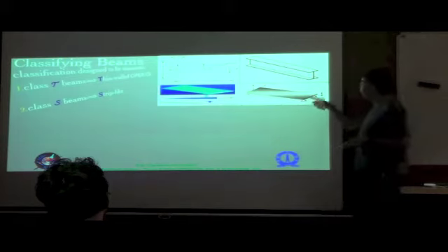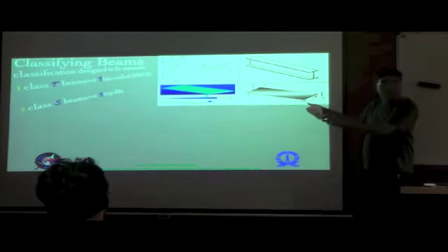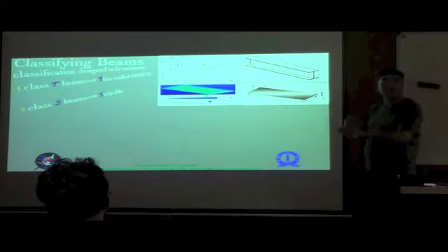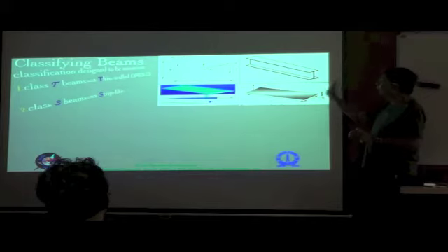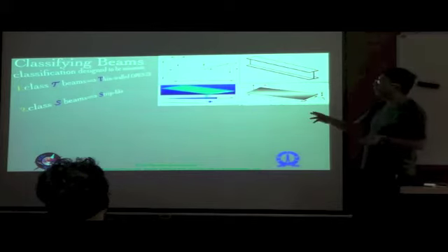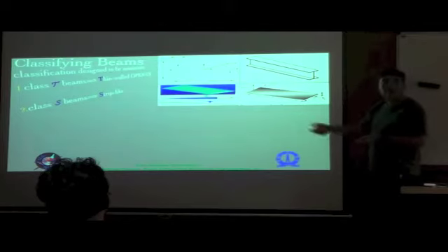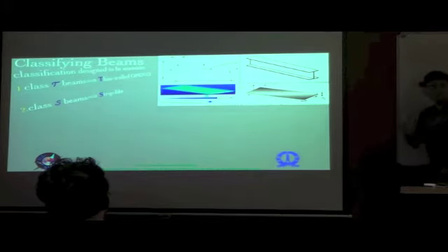So of course we have the thin rectangular cross section, and in each one of these situations, it can have an initial twist, it can have an initial curvature, etc. It is irrespective of that. What we are focused on is just the cross-sectional geometry, used as a basis of classification, which in turn also turns out to be equivalent, as I said, to the asymptotic theories for each one of them being different.